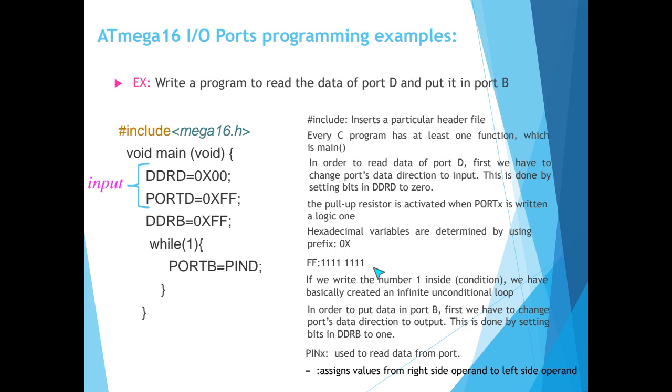Then you see that we configured port D as input. We configured port B as output, and now we need to read the data. For reading data, we use which register? Do you remember? For reading data, we use the pin register.